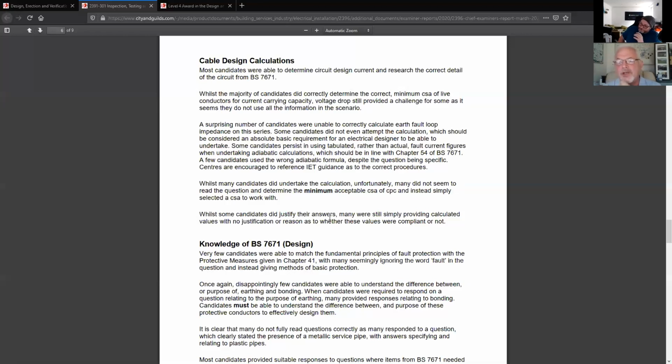Take a shower circuit in a loft that's got loads of thermal insulation in it, with the cables grouped with several other circuits running through the loft, and then thermal insulation over the top. Somebody's put it in a bit of 6 mil or whatever. Then maybe somebody's changed the shower to a 10.5 kilowatt shower, or simply changed the demand on it. So I think there should always be, and if you look at the certificates that we produce,